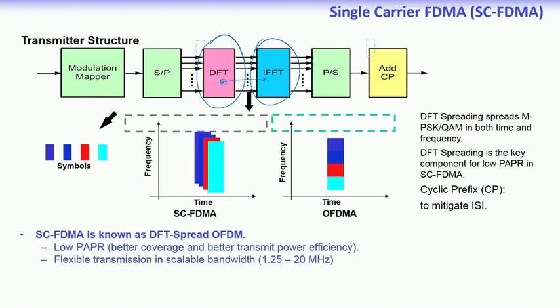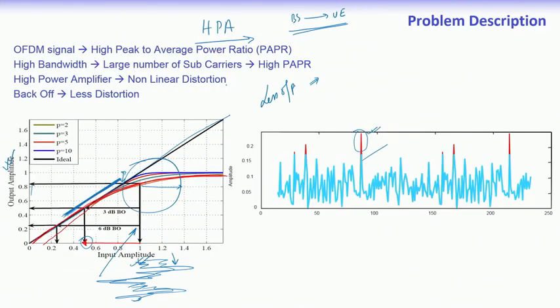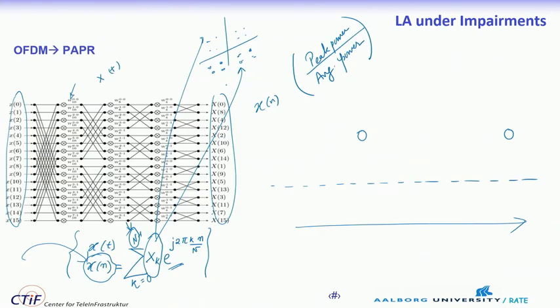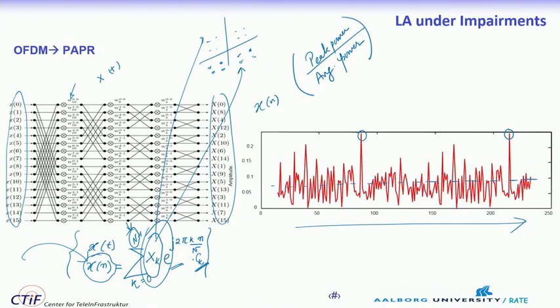Now, there is a genesis for this kind of study. Since there is a combination of these weights that causes a large variation, the large variation would happen if they add up in phase. If by some mechanism the in phase addition can be destroyed, then the fluctuations or variations can be made less. In order to do that, at every point one can think of multiplying by Ck, where Ck is some code sequence. The code sequence can be taken from various aspects: one could be a Hadamard code, or a DFT code.